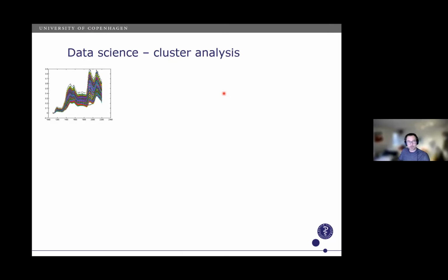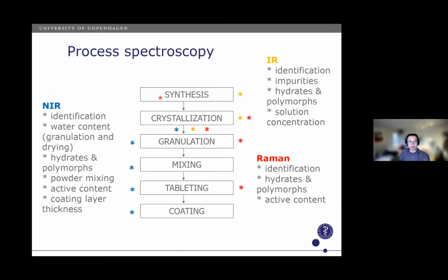Yes, indeed, that's a good question. This could potentially be an end-to-end continuous production line, and this would work out fine, or it could be a continuous granulation process. Many of these techniques are used in continuous processes. I would say that it would be very difficult to do a continuous process without any process analytics. It is a key aspect of continuous processes that you measure the product quality while you are processing.